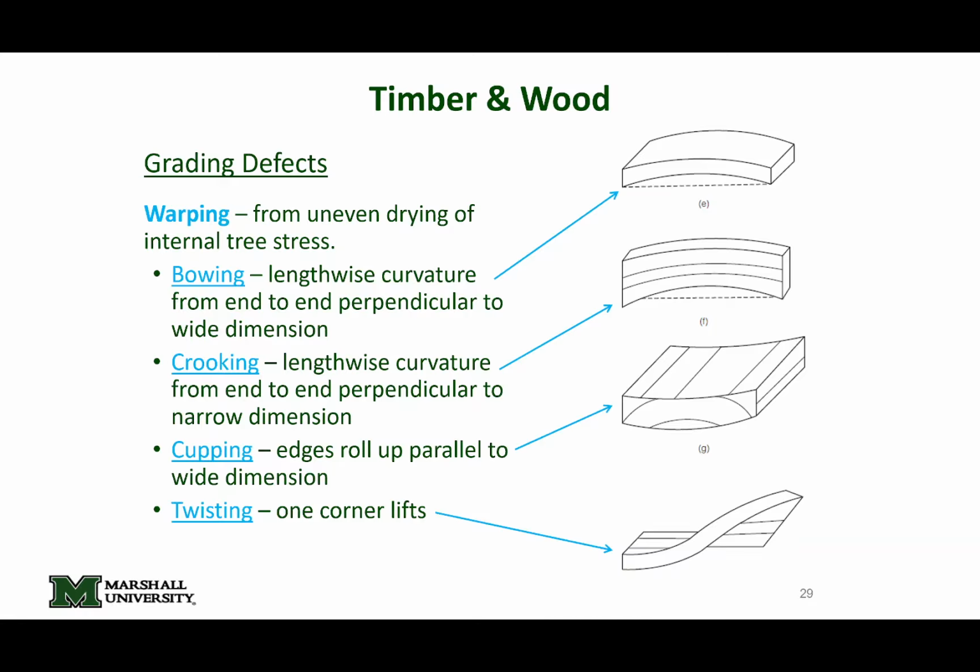The tree wants to stay like this, and so when you cut it into a rectangular cross-section, it's going to kind of bounce back, okay? It's going to change a little bit. It's almost like these fibers are a big old rubber band stretched around the tree, and then you cut it out, you're kind of relaxing it a little bit. So it's going to deviate from a prismatic cross-section just for that reason. That's called a release of residual stresses, okay?